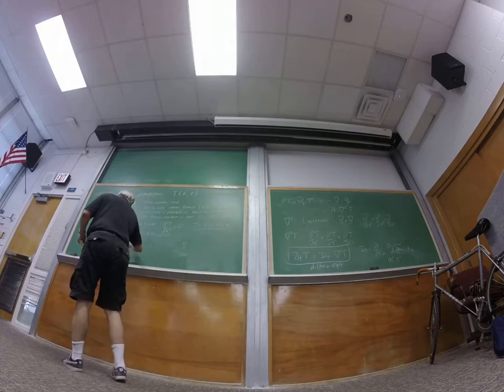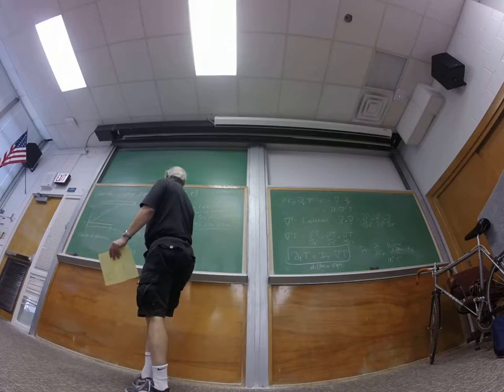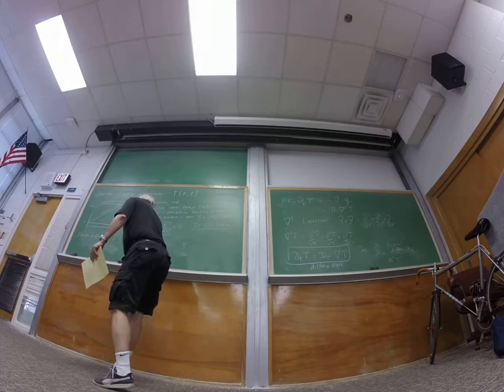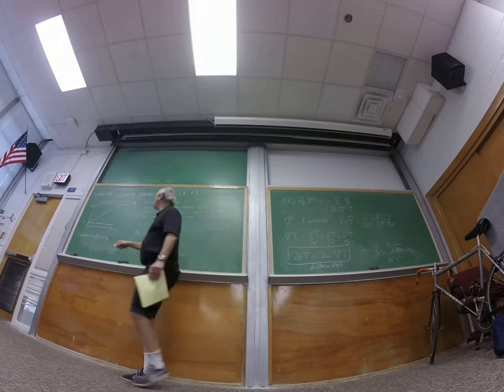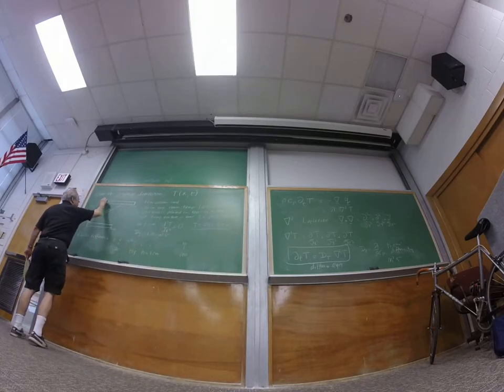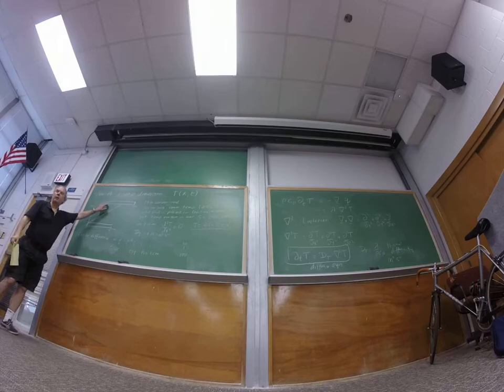So when I get to actually solving it, I'm going to start off by trying something that seems to me to be fairly sensible. We'll try h is 1 centimeter. It's a 30 centimeter long bar. What I'm saying is I'm going to divide it up into 30 segments. What I'm assuming is that there isn't too much variation between those two segments. It doesn't really matter because we can always go back and increase the number of segments if we haven't taken enough.